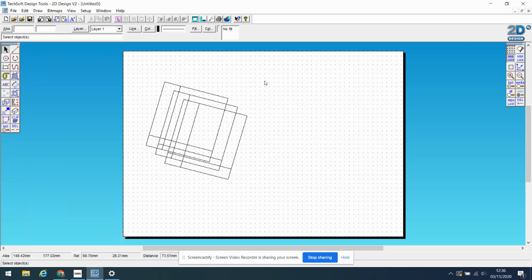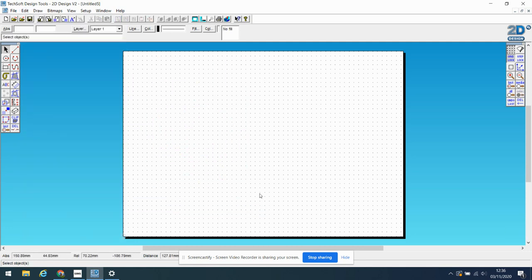It'll only undo once for you, okay? So what I want you to do, get your shape tool, left mouse click once, send your REL to 0 and 0, do it to 60 and 60, click. You're going to copy that once,